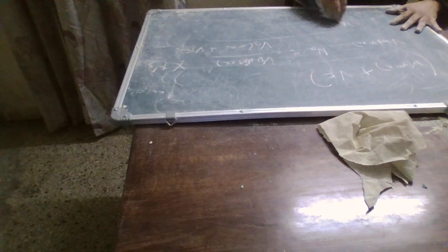The minimum number of auxiliary winding turns is what? We have taken a VDD max. Here again we will take VDD off plus VDD PCT plus delta V, by VO minimum plus V forward. Again the secondary number of turns has to be multiplied by this, and this would give the minimum number of auxiliary winding turns. The previous one gives the maximum number of auxiliary winding turns. So this must accommodate the highest VDD and the threshold also.